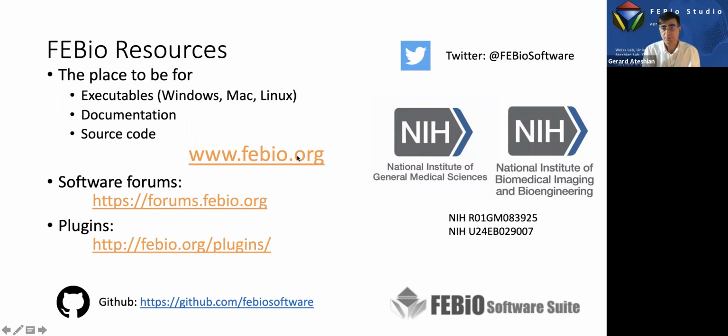We have an FSI module and a biphasic FSI module, but really what you want to do is an FSI module where you create a solid structure which represents the porous structure. So you explicitly model the porous structure, and then you put a viscous fluid in it, and then you apply a pressure upstream and you measure the flow rate. Then you extract the hydraulic permeability. So the answer is yes, but not using the presentation I showed you today. It would be a different lecture. It would be a webinar on fluid structure interactions.